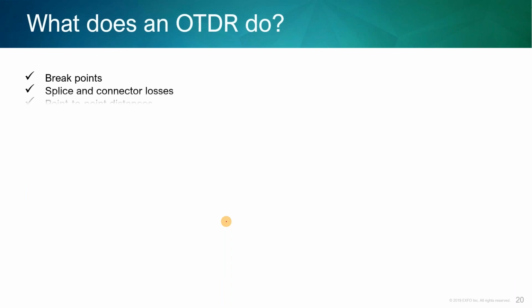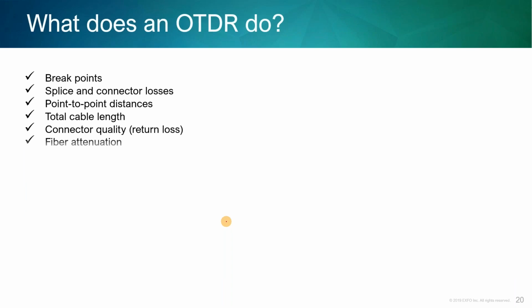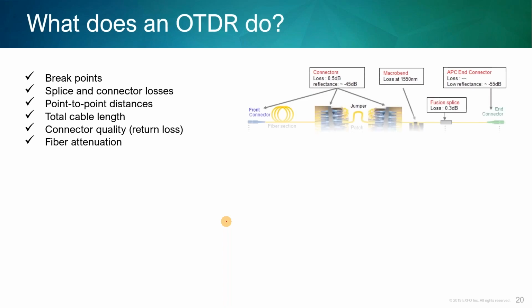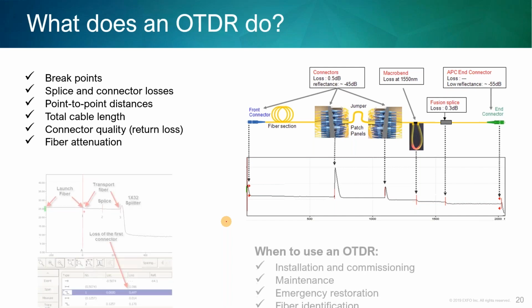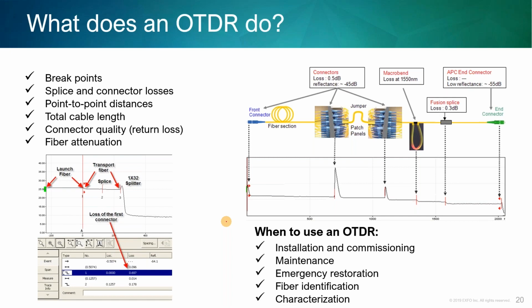So basically we use it to find a backhoe sticking up of our cable, right? That's one of the big uses of it for finding, a squirrel having lunch, dirty connectors, bad splices, bad fiber management, bad placement issues, just bad cable in general. It helps us identify those things if we have it set up correctly. And it's used by all groups during installation and construction, during maintenance, disaster recovery, requalifications, all of that stuff, right? It's really important that every stage of this understands how to test.